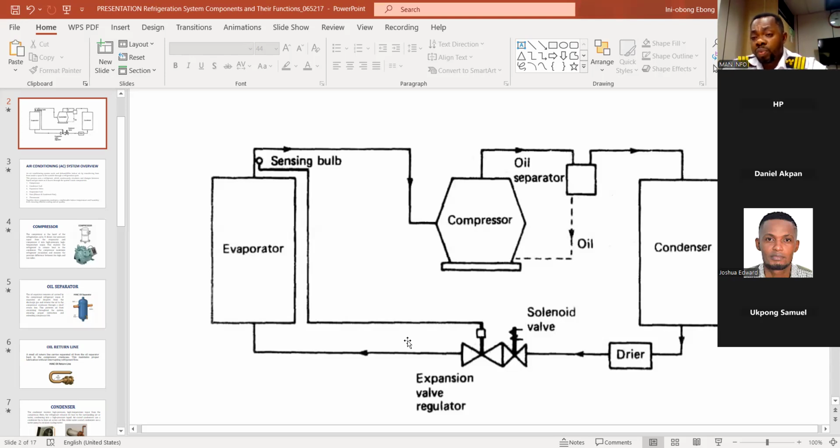For you to solve a problem, you should understand that problem. If you don't understand it, you will not be able to solve it. You might end up compromising the system or choking the system with refrigerant, because our mentality is already tuned to think that when it is icing, the system is low on refrigerant. So you need to troubleshoot and check.